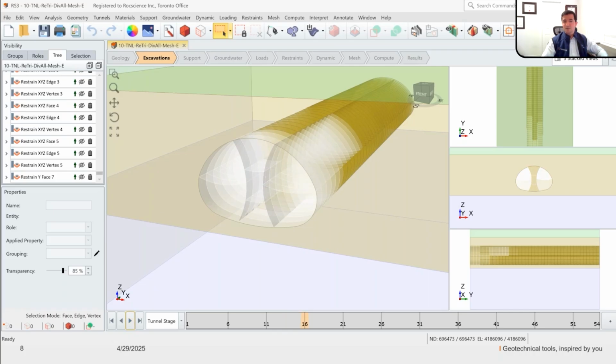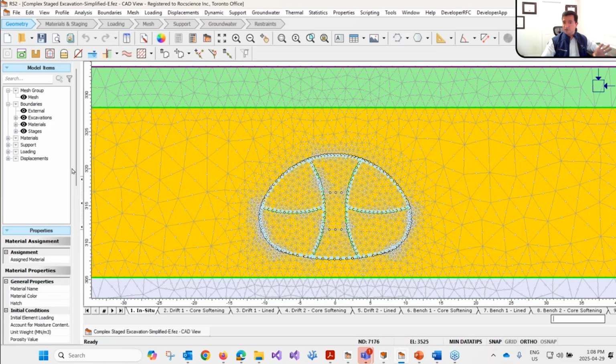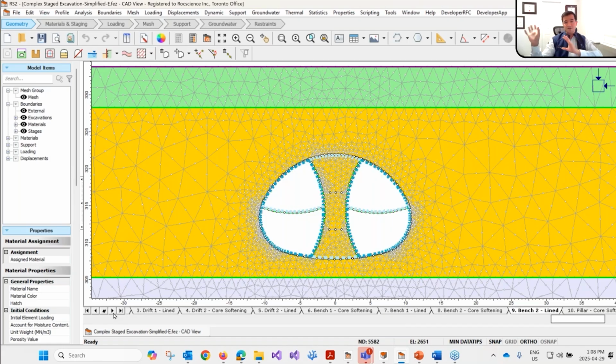so this is the geometry that I have. We have that core opening, for example, liner coming in, another core opening, liner coming in, different region core opening, different region liner, and gradually you're simulating the same effect of 3D with that stress relaxation, and you time when your supports are coming in to get that full excavation. There you go.